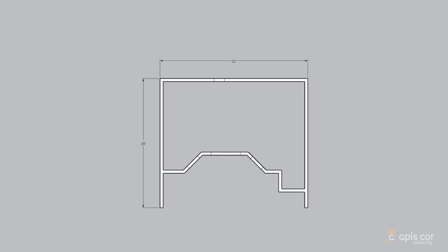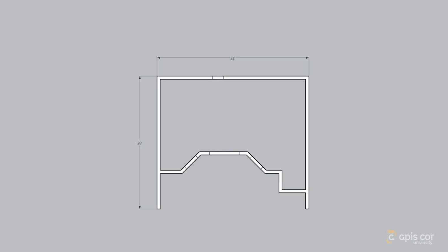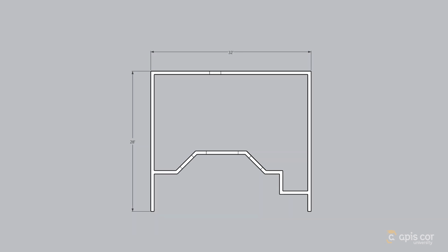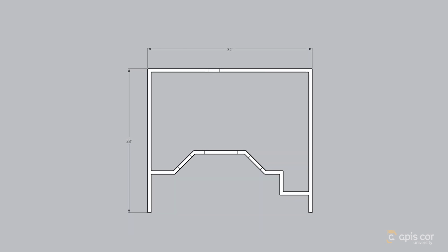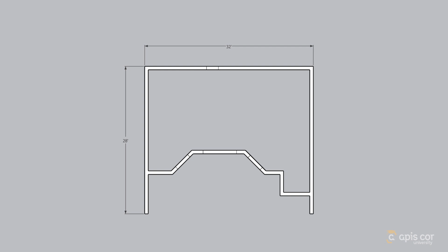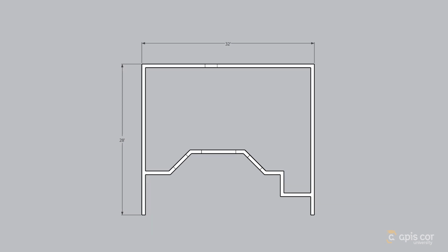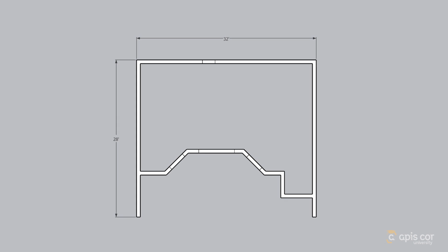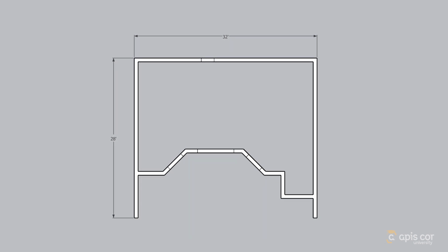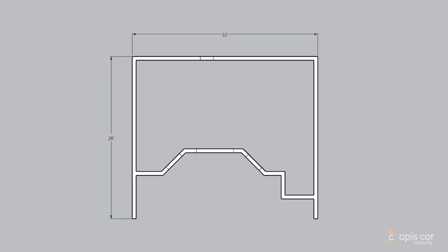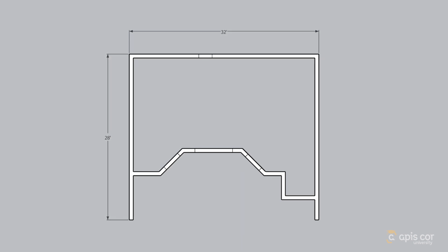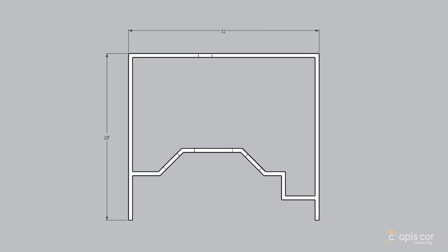You know that the maximum print radius is 16 feet 5 inches, which means the maximum print diameter is 32 feet 10 inches. With this in mind, you draw a rectangular house with exterior walls measuring 32 feet by 28 feet, and you choose these lengths because they are both less than the maximum diameter of 32 feet 10 inches. Do you think that this home can be printed using a single print radius?